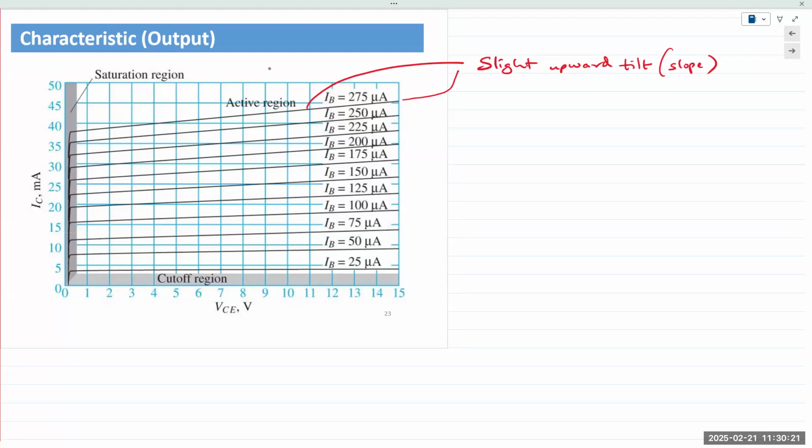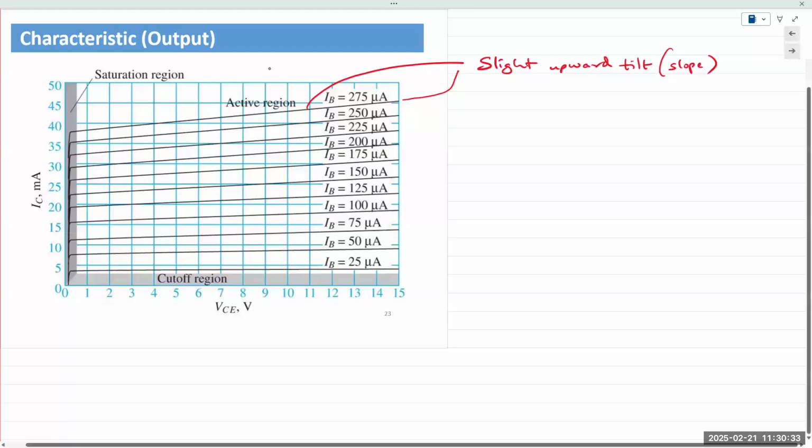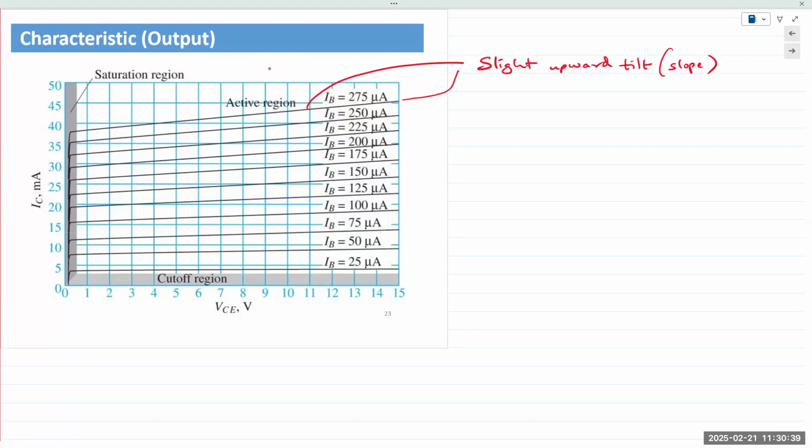So if you're trying to find the output voltage and the output current, meaning the Q point operation, we can use load line analysis by first applying it to the input side, then transferring those data points onto the output side. Later on, we will do an example on how to do that. But the process would remain the same.